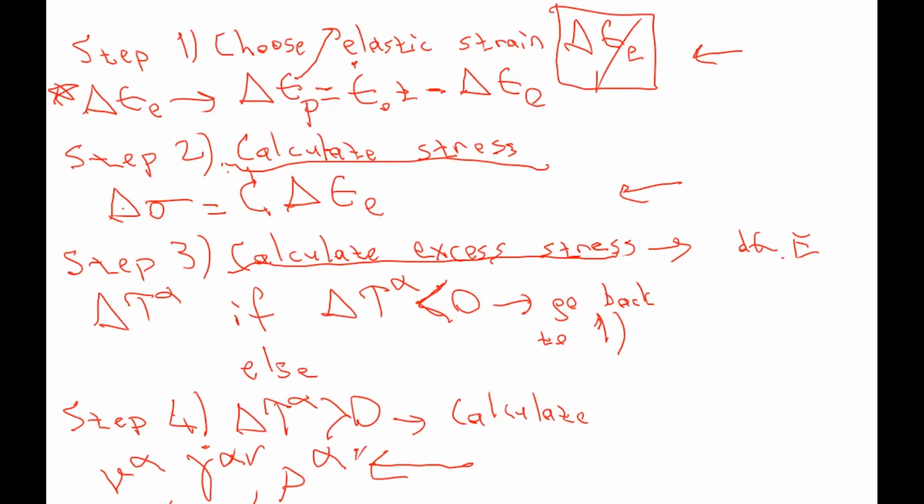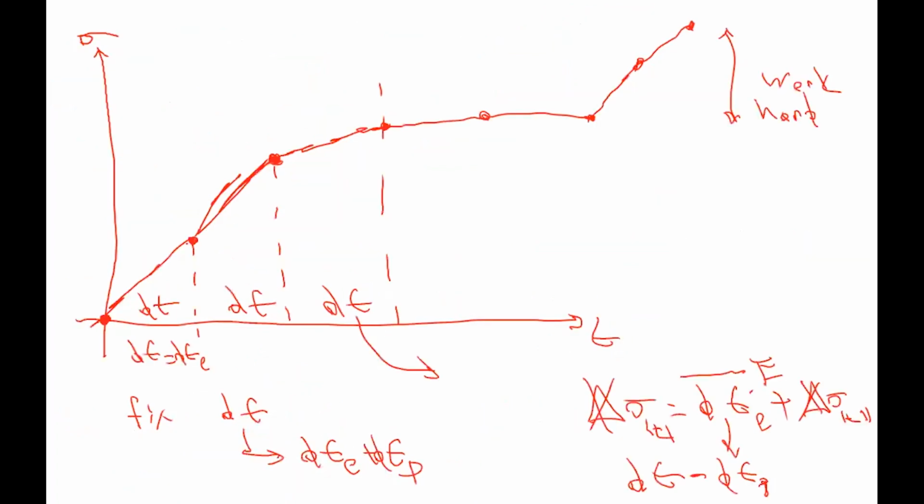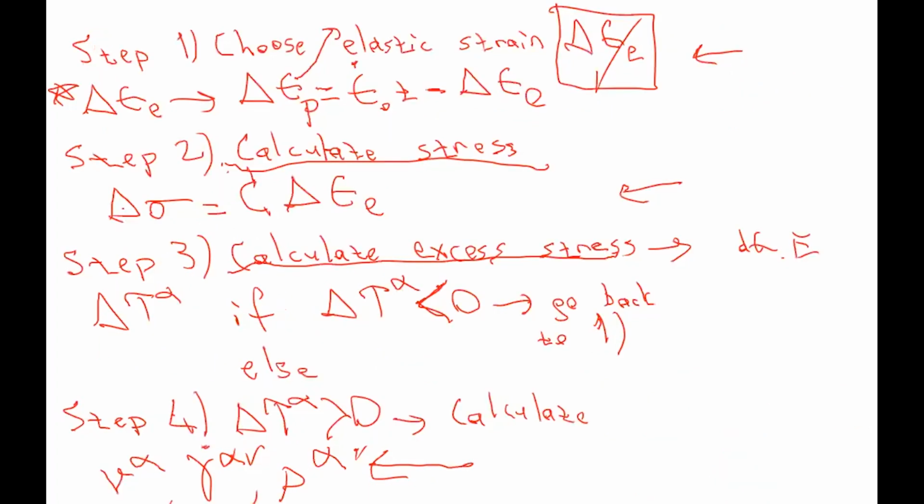Once you calculate your plastic strain, you can just compare the one that you selected as a plastic strain and the one you calculated. If they converge, if they are equal to each other, then you're good to go. If not, you need to choose another elastic strain.